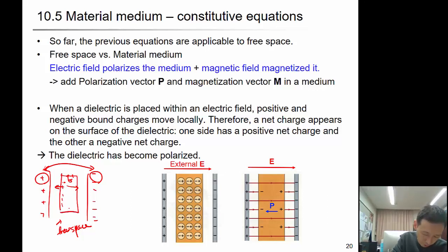Clay has negative charges on the surface, and if the current is moving, then this minus charge will be here, and then will be here, so it will locally concentrate, but in harmony with the external electrical field, and that's called polarization.